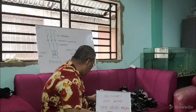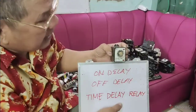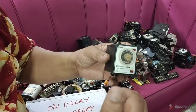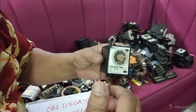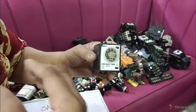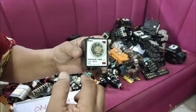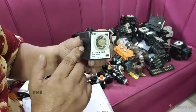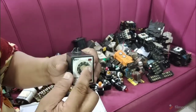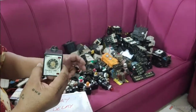Okay, then that is what we call electronic timer. Then we have also another timer here, like this. This is the sample, star delta or Y delta timer. Usually this timer is used for the reduced voltage magnetic starter, Y delta magnetic starter. Because from Y, it will set automatically to delta. So there is really a delay, so you need a transition time. So you can use this timer. This is only intended for star delta starter. Anyway, this will be explained when we touch the Y delta magnetic starter.